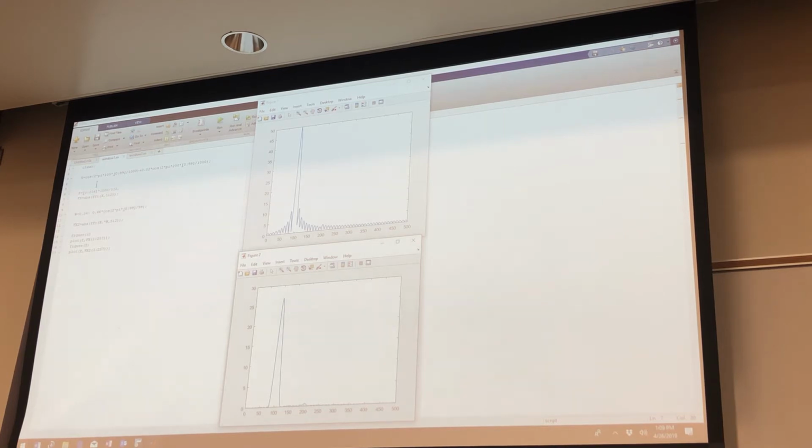Understand? You notice right here, here he creates the F, that's the frequency value based on scaling. Remember, what you actually have is, when you have a sampled frequency, the actual frequency can be extracted from that. It has to be given though. And then what he has here is a simple FFT of this function x, and the FFT is a fast Fourier transform. It's the same thing as a DFT, only the number of samples is 2 to the n. This is the weighting function. This is going to be the window.